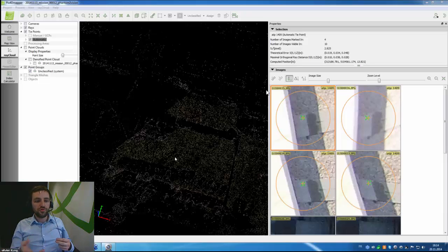If there is a huge concentration of cars, a lot of traffic, then the mosaic will probably not be very good. But if you have not too many cars passing by, you actually will get very good data, and you can use the mosaic editor tool that we have inside of Pix4D Mapper to make sure that you are choosing the right part of the highway without having ghost cars in it.